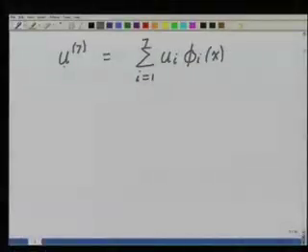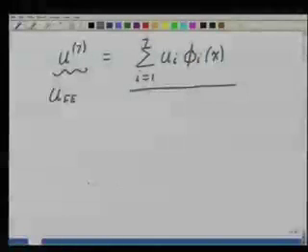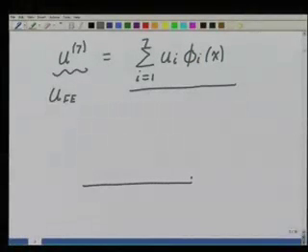Now I will not carry this upper subscript 7 throughout my presentations from now on. I will switch to UFE, where UFE will stand for the particular series that we are talking about. Okay. Now, this is the representation of our finite element solution. So how are we going to do this at the element level? At the element level, we have to define the element level shape functions.